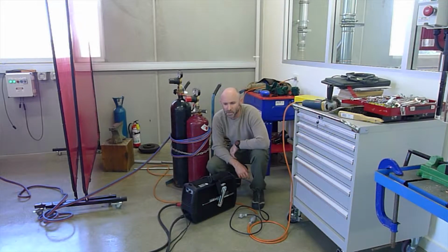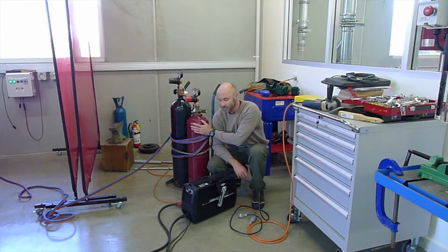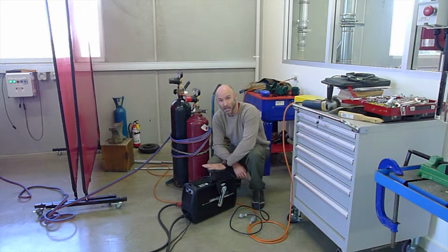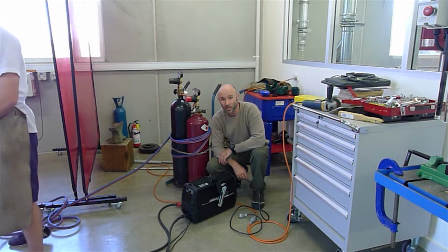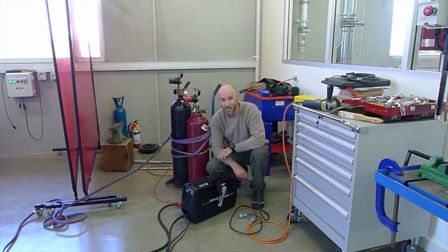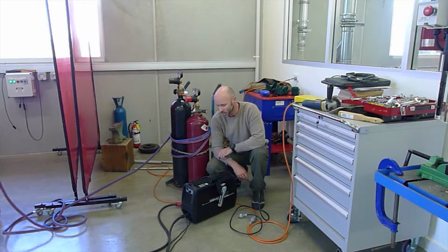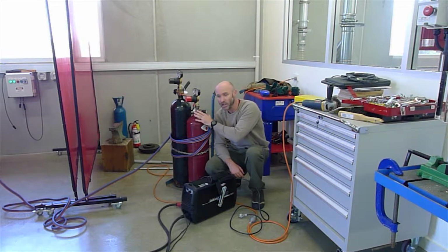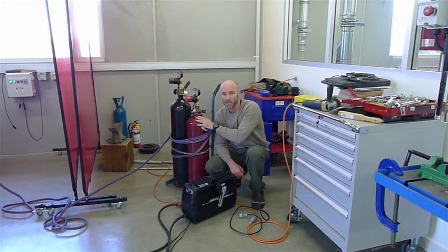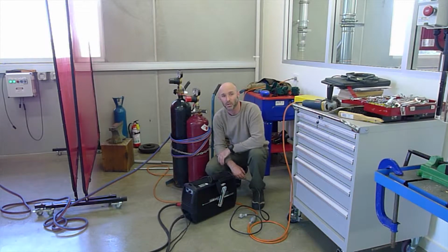Two other pieces of equipment that are used in schools for cutting metal is the oxyacetylene, and more recently schools are getting these plasma sets as well. Now these plasma sets are fairly inexpensive, they only cost about $800 each, but there are much larger versions of this that can cut much more significant amounts of metal. The oxyacetylene is quite useful as well because not only can it be used for cutting, but it can also be used for brazing processes, heating processes as well, which is what it's being used for right now.